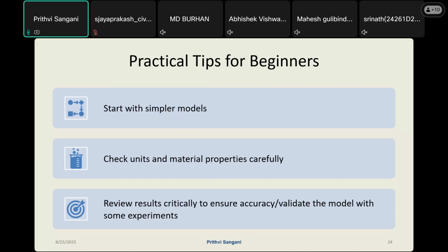Let us say you give your units in terms of length as mm, and stress as Newton per mm square. In forces it's Newton. Then your results are going to come in terms of Newton mm for moments, Newton for shear force, and mm for deflections. So you have to be consistent from the beginning. There is nowhere where you can click or check the units. It all starts from the time you are inputting your units.